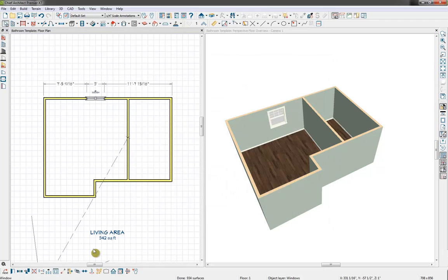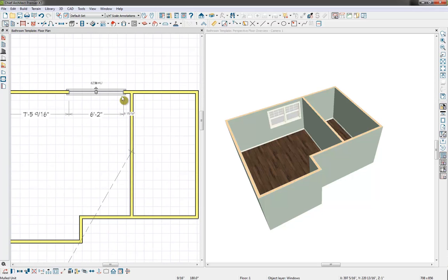And then I'm simply going to use my edit toolbar to copy and drag out a copy right next to it. We'll bump it up against there. And then once I have two copies, I'm going to hold down my Control key to select both together, and I'm going to mold them together. So they're now a mold unit. And now that they are a mold unit, I'm going to dimension the two of them together. So we'll select there and select that dimension, and I want it to be exactly 8 inches from the wall. There we go.